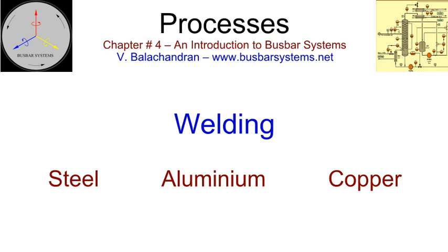There are guidelines for effecting the welding of steel, aluminium, and copper. These include the type of edge preparation, root gap, preheating temperature, the diameter of filler rods, gas nozzle diameter, type of gas, gas flow, welding electrical parameters, etc. Every industry must develop its welding manual depending upon the nature of the job and ambient conditions.